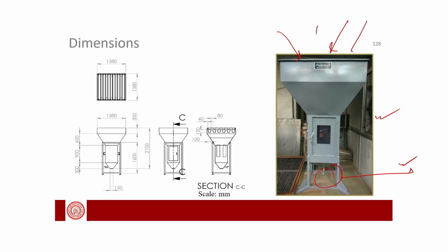The main thing is that we have to lift the water and fill it. At the first stage the water is transported through wicking action, and then for filtration, the pressure we are getting is the water head pressure, and that pressure will help in filtering water through the cartridge.